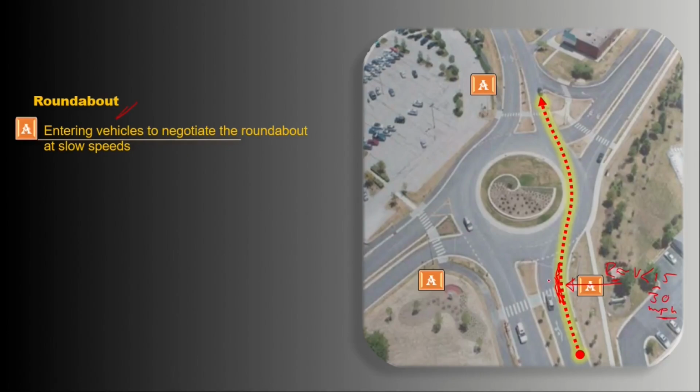It is necessary, but not enough. The speed between consecutive curves and also between conflicting movements has to be consistent. Normally, a maximum difference of 10 miles per hour is accepted.